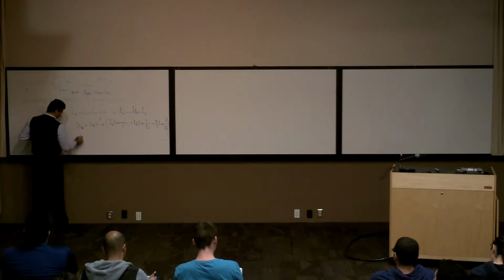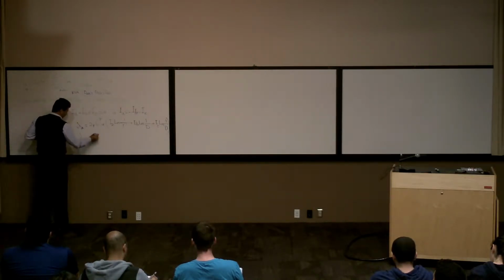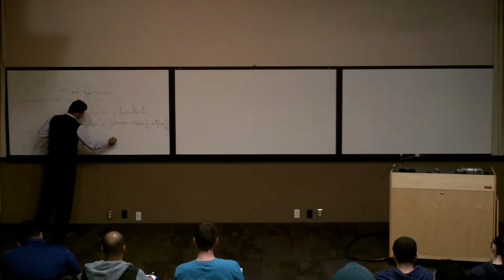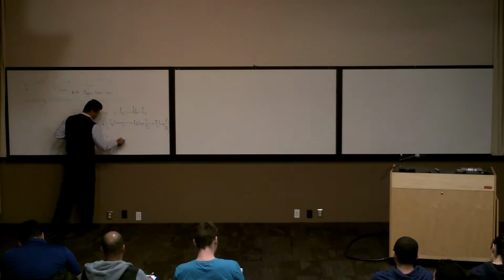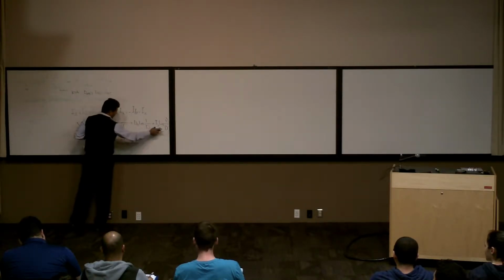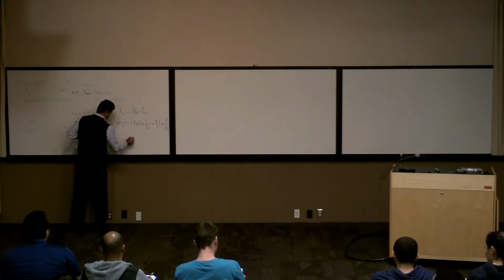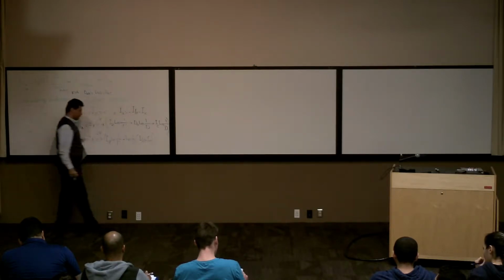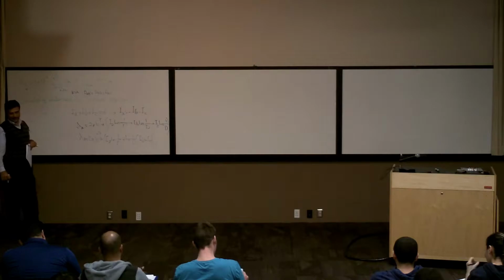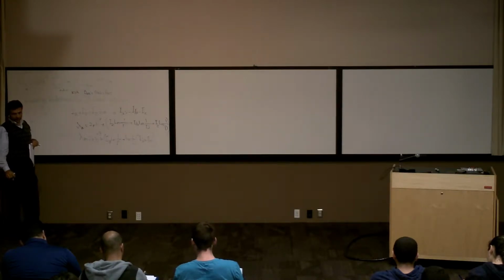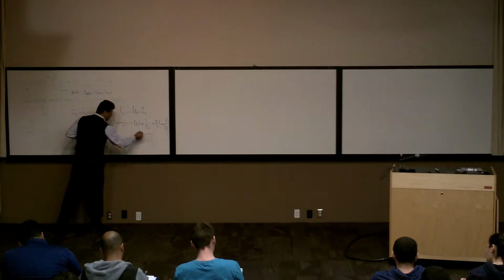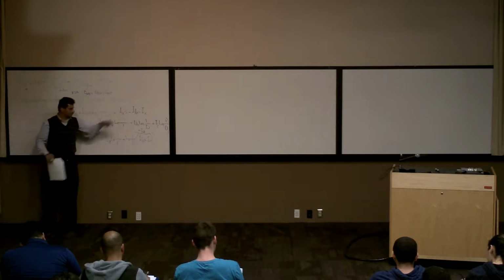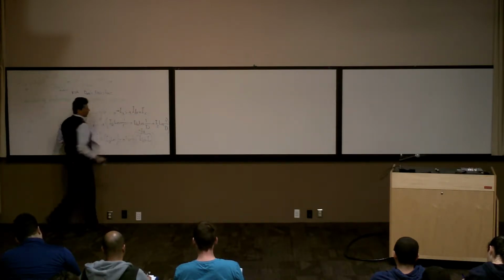Do it this way now. You say lambda A is going to be 2 times 10 to the power of minus 7 times IA ln of 1 over R prime plus, let's factor in this. It's going to be ln of 1 over D times IB plus IC. Right? Because I factor in ln of 1 over D. So, how much is this one? This is minus IA, right? Look at here. I can say minus IA is equal to IB plus IC, right?